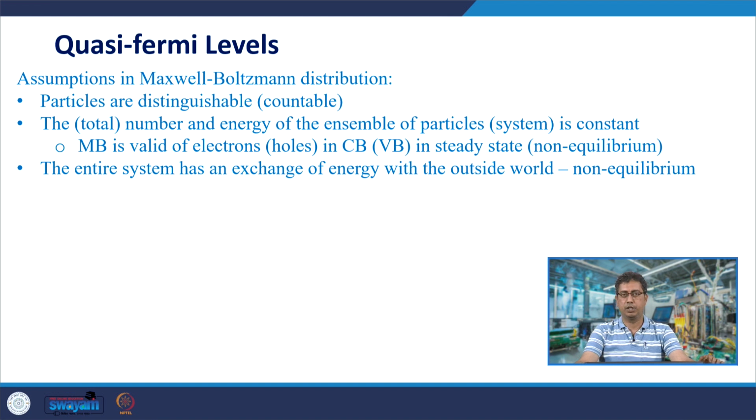change the gate voltage, the silicon region or semiconductor region of the MOSFET device would be in quasi-equilibrium condition, where the semiconductor region of the device would function as if it is in equilibrium condition. Quasi-Fermi levels of electrons and holes do not separate, and locally they would act as if equilibrium condition is there and you are dealing only with the Fermi level which you are used to. So, what are these quasi-Fermi levels?